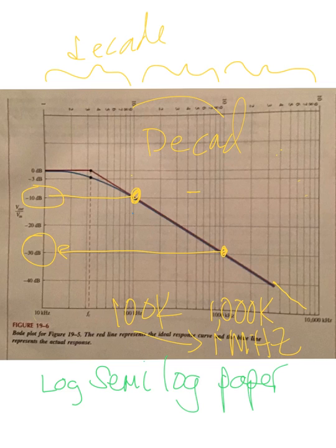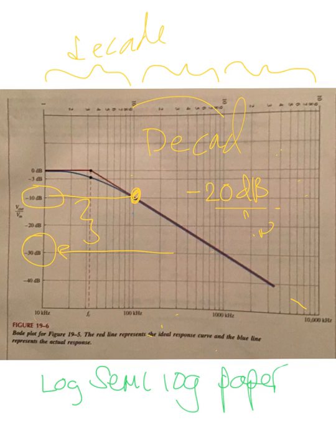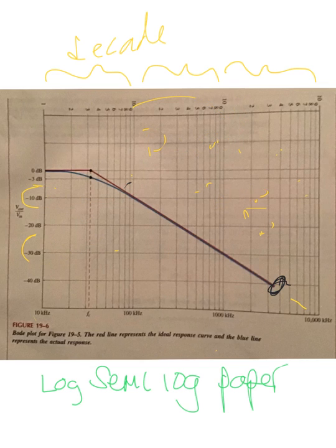It's actually minus 20 dBs. The difference here is minus 20 dBs per decade, as I predicted would be the case. So that line, once it hits this black spot right there, is pretty consistent all the way through that straight line that's drawn there. I mean, you can take a ruler and just draw a line, because that's what your resistor capacitor network is going to provide you in terms of performance.